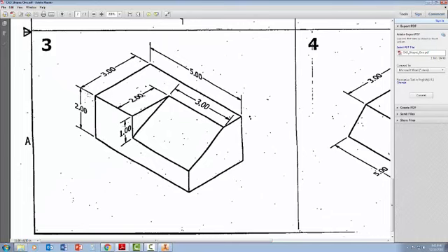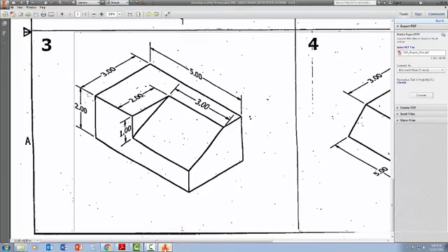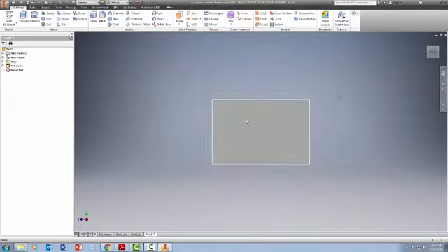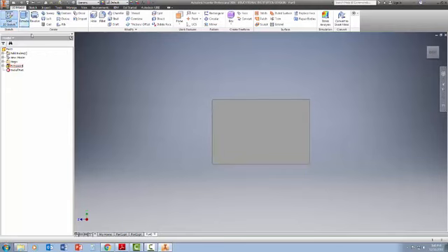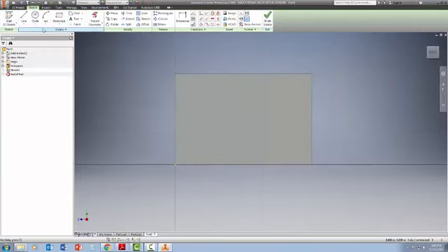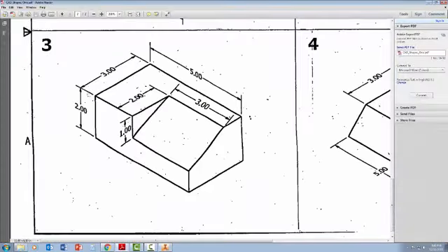And now we have, interesting, now we have a little bit of a piece missing on the front here. Okay, so let's work on this. We're going to work off of this side, the right side. So what I want to do is start a new sketch on this plane. I'm just scrolling with the ball on my mouse. Hit my line tool. I'm going to start here, and I'm going to come down a certain distance. And what's that distance? It's 1 inch. Okay, so I'm actually starting over here. It's going to come down 1 inch, and we're going to go over 2 inches.